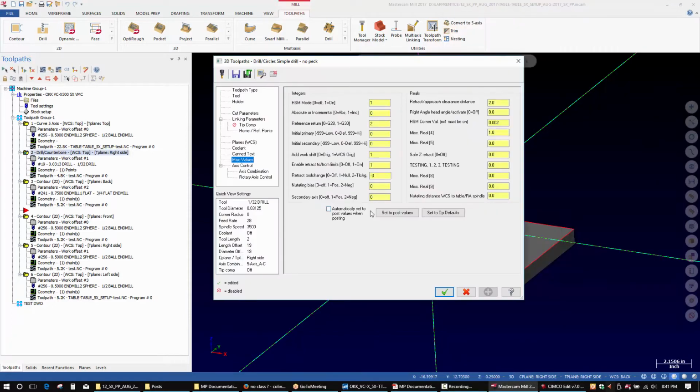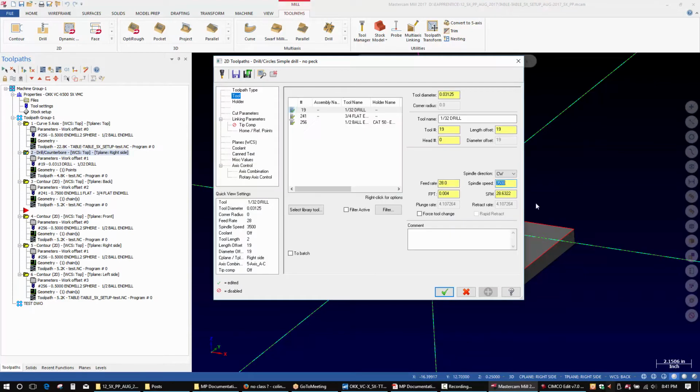But what about this? What if I go in there and I say, you know what, I'm going to spin it at 3357, and I really want 8.5 thou per rev. 0.0085 times 3357, and I'm getting 28.5345. Okay?